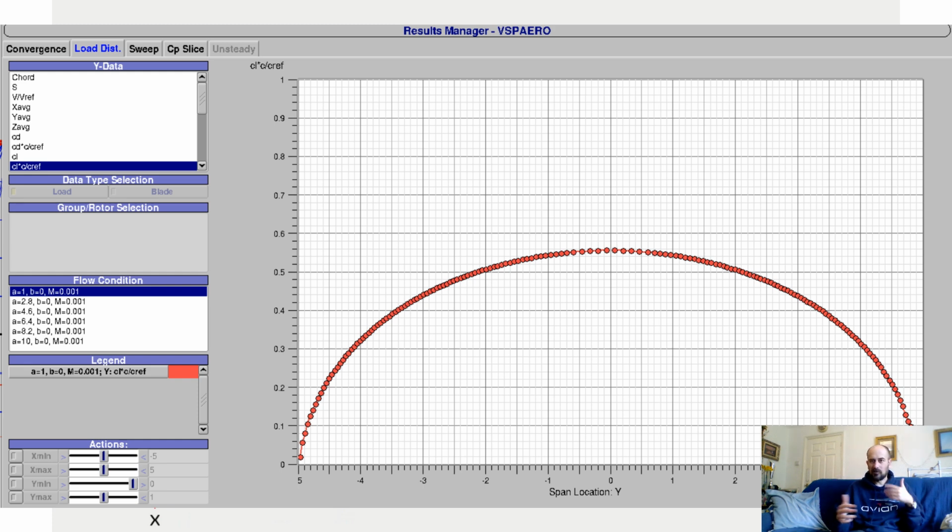Now, if you start getting into non-planar wings, so we have a variation in dihedral along the wing, or you have winglets on them, it can be different, and the perfect lift distribution in those cases isn't elliptical, but there is still an ideal lift distribution. There is a perfect lift distribution that if you've got the lift spread over the wing in this way, that's the best it can be. There is no way to improve on that. And the thing is, that is potentially something you can calculate as well.